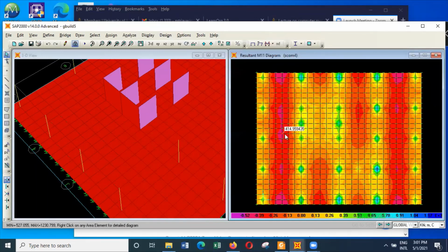So if you look at the bending moment values, they are in the range of 400, 500 and so on. So if the bending moment with the torsional effect goes up to about 600, bending alone is about 500, and if it goes up to about 600, M over bd squared is 600 into 1000 divided by 1000 divided by effective depth of 1400 squared. So you get a bending moment of 600 kilonewton meters, and d is about 1400. So the M over bd squared value is very low.